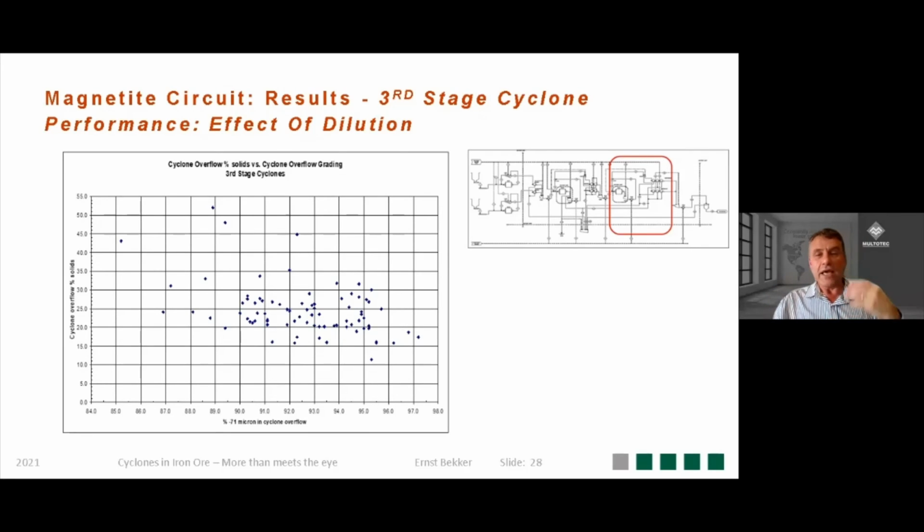That's what we did. Add more water in the tertiary milling circuit, and cyclone overflow percent solids came down because we're adding more water, and we could see that the minus 71 content started to increase. But again, up to a point, and then it stops. So it's like a plateau where it then starts to level off.